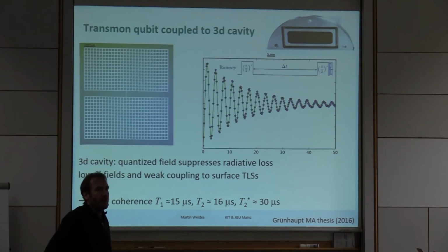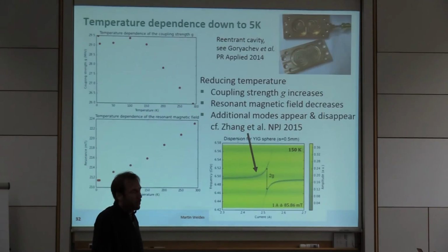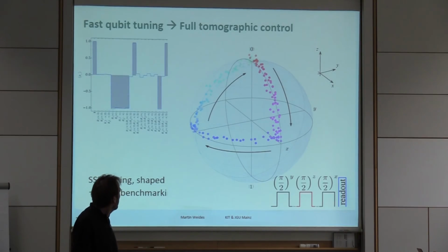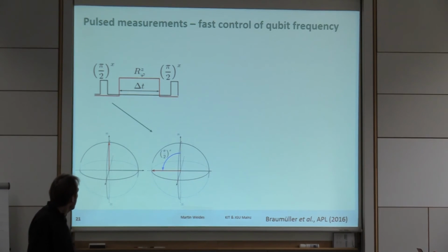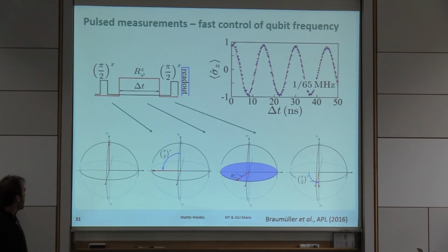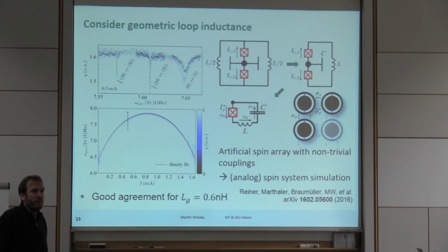Between your qubits, you had both electrostatic and inductive coupling. So what's the strength of the coupling? It depends on geometry. It's 10 to 30 megahertz. We're doing simulations on it, so it's not strongly inductively coupled or capacitively coupled, but they're on the same scale. It really depends how close you bring it together. So the same size, say 10, 15, 20 megahertz, both.